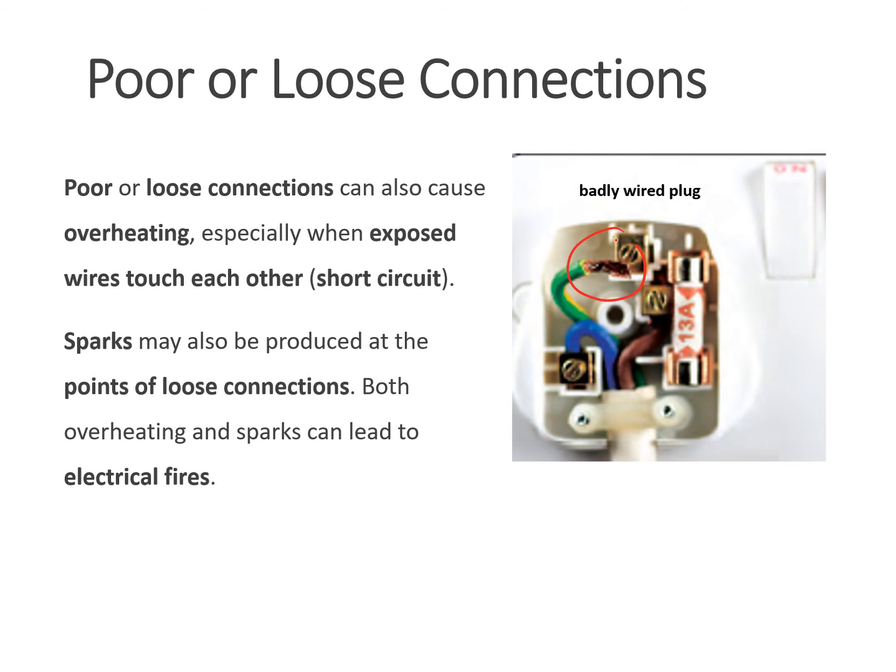You look at this part here. Okay, a lot of loose wires. And so what happens is if you have a lot of loose connections, the current can sometimes form a spark and jump over to this side and jump over to this side. So then you see sparks inside, because when the connections are loose, then you get bare wires.